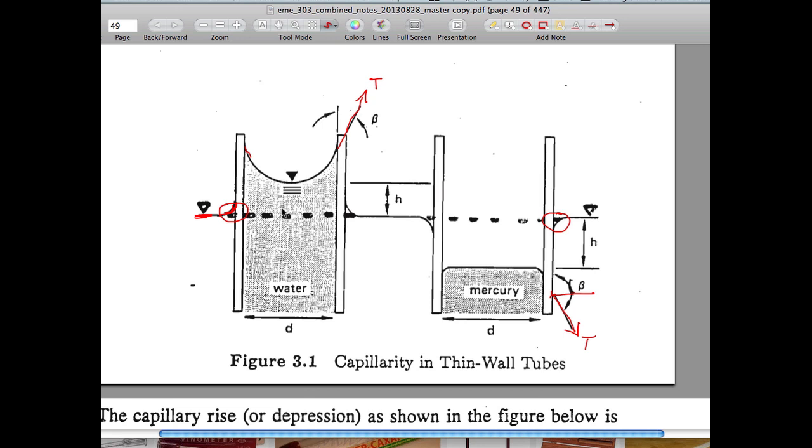And the key observation, as we'll find out later, is that if you look at moving in a fluid from one location all the way to another, and you could make that journey through the fluid alone, then on any horizontal plane, the fluid pressures within that fluid have to be the same at each elevation. And so the fluid pressure here, which has to be only atmospheric, because that's what it sees, has to be exactly the same as atmospheric at this point here.